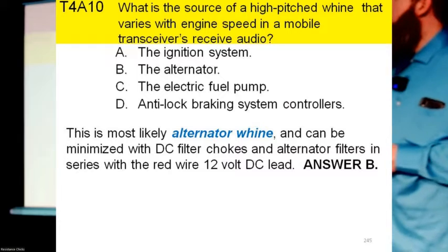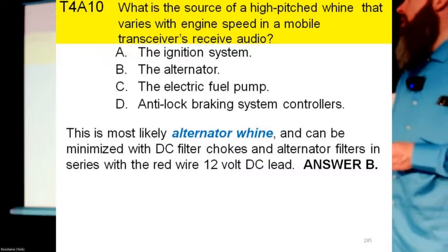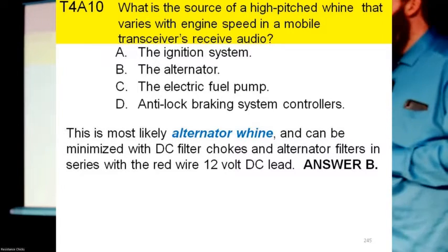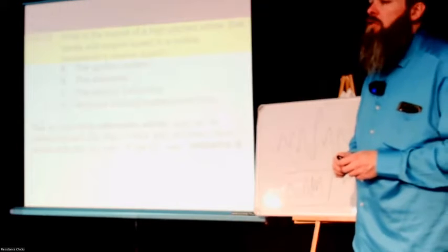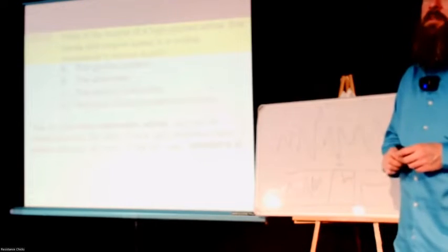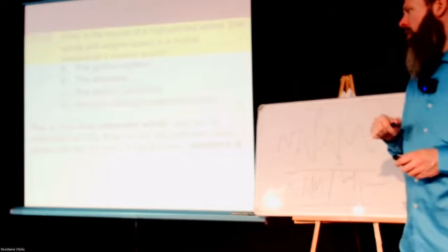What is the source of a high-pitched whine that varies with engine speed in a mobile transceiver's receive audio? That's the alternator. So your alternator is making noise. Yep. It can be eliminated with DC filter chokes.